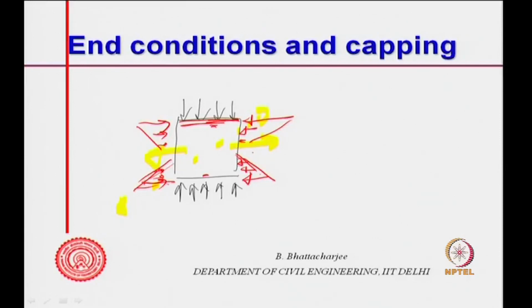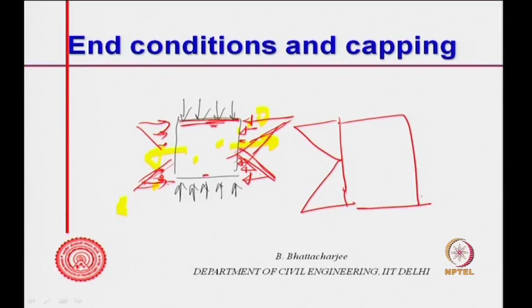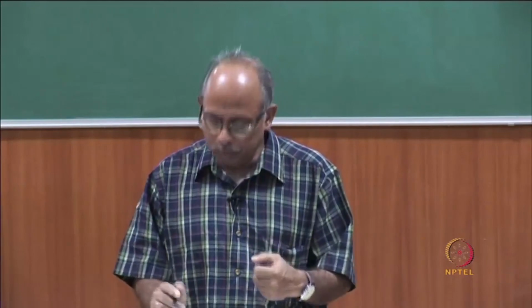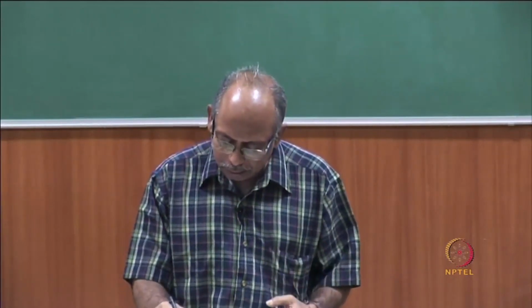So, you do not have really a purely uniaxial situation, you have a situation where there is some sort of force acting onto the specimen depending upon the type of specimen or L by D, up to some height, there is a force acting like this also. This will depend upon, this is your L and this is your D, D is the dimension of the cube. So, if it is D and D, then there is somewhat overlap, we will come to that just now. So, you see there is an opposing force to the movement, horizontal or transverse movement, both in this direction as well as in this direction there will be an opposing force.